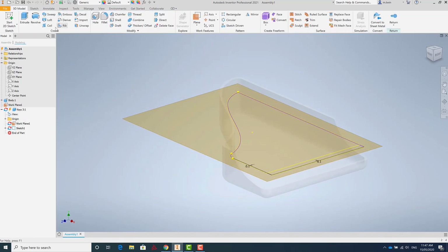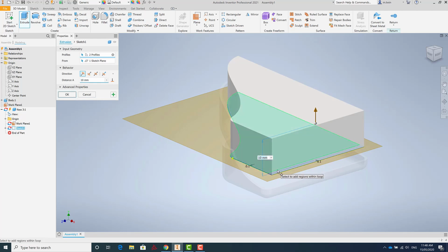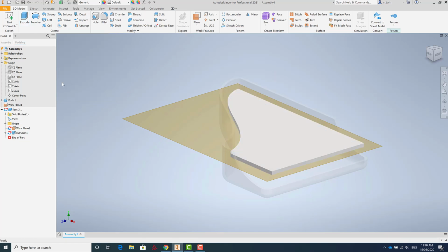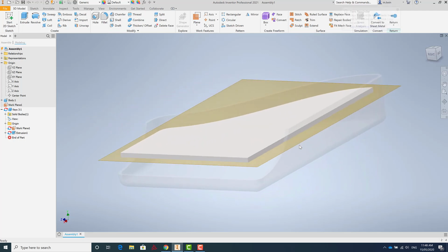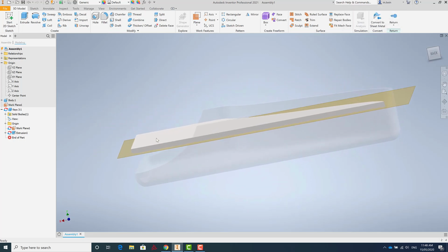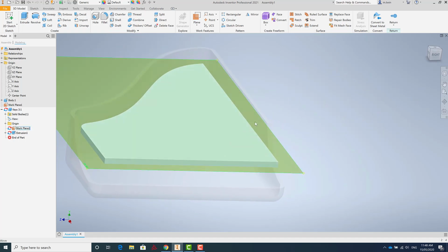And if I go to extrude, I should be able to extrude that shape. It's offering me that as an option. It also should offer me the whole thing. That's what we want. Now the sheet metal that we want to work with for this is 1 millimeter. So I'll extrude this a distance of 1 millimeter. And we'll be able to cut out that metal on our water jet cutter here at the tech school. Great. So we've got our 1 millimeter thick steel, which is actually a lot thicker than our 0.7 millimeter wall housing, but that's okay.